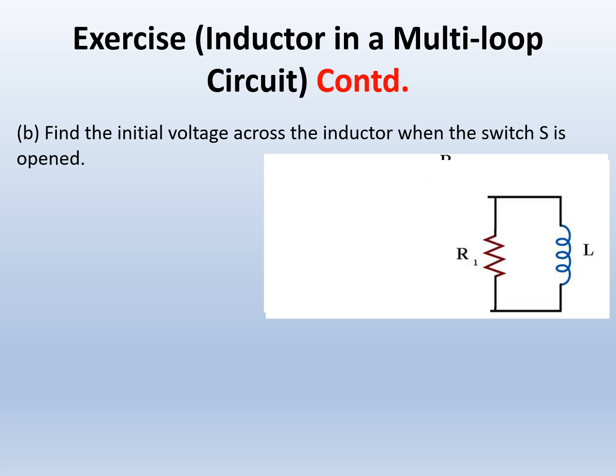Now the battery is not sending a current through the inductor, and therefore the magnetic field in the inductor stops, and the magnetic flux is going to be zero, and the inductor does not like it. So it induces a voltage to reproduce the current the battery was sending, and that current is now going to go through the loop created by the inductor and the resistance R1.